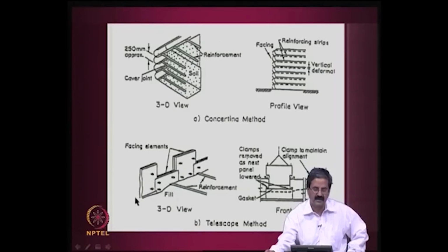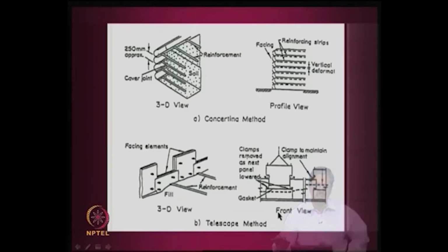So, for which, for example, there is so much tensile force. How do you calculate the tensile force at any point? If you are using geotextile, geotextile has more tendency for deformation. So I use Ka into sigma V as the horizontal stress acting, and suppose SV is the vertical spacing, and I am taking per meter length of the geotextile. Ka into sigma V into SV will give me the horizontal force acting at any point, is it not?